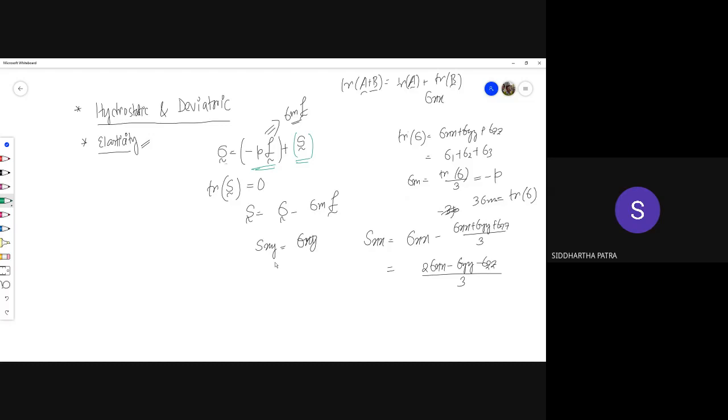And as it turns out, metal plasticity is kind of volume preserving. Don't take the word literally. It's not that the volume of a metal cannot be changed through plastic deformation. That's not true. But when compared to the other components of the strain, for example, the normal strain, the volumetric strain is much smaller.